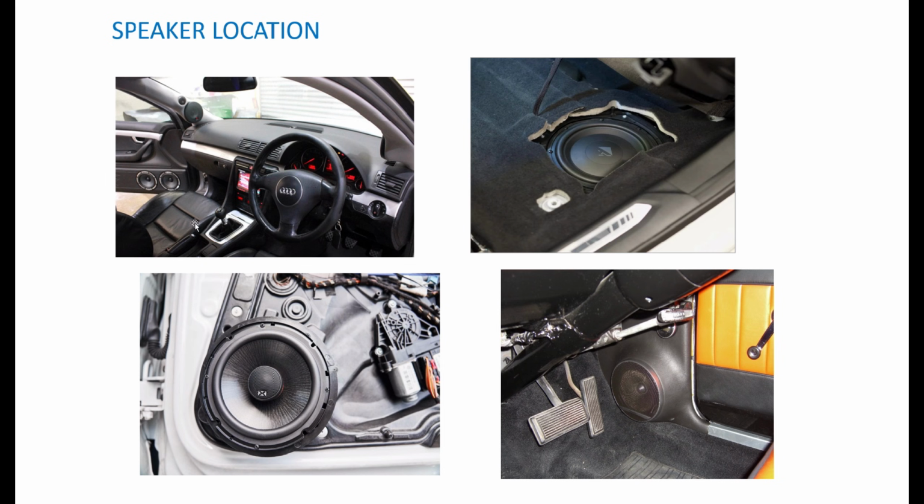So one of those is how big are the pillars, how much room do you have in the door cards, how much room have you got underneath the seats, can you fit speakers under the seats, is there enough clearance in the door cards, is there enough depth so that you can mount a speaker without the speaker hitting the window mechanism or interfering with stuff in the door itself.